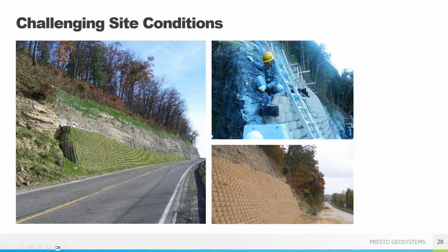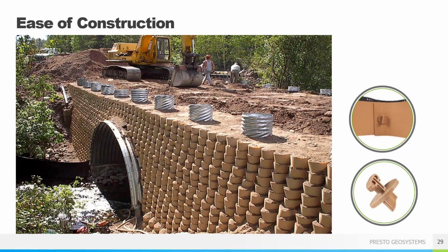And here's another project over in Japan that we recently constructed. So the geo is just really a fascia. We can help you with those types of projects, more or less a gravity wall, because it is a stable system. But we do like to put some type of a reinforced zone behind it just to make sure we maintain drainage.